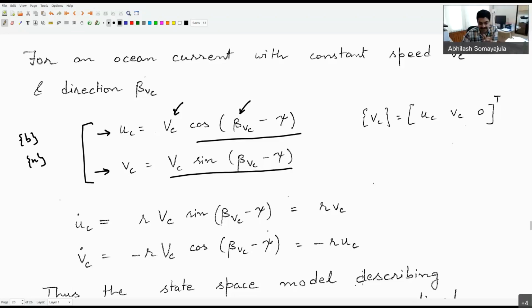Just understand that when I'm taking a difference between the actual direction of the current and my current heading, that is telling relative to my ship's bow where the velocity is pointing, isn't it? Then what am I doing? I'm taking its components with respect to that angle, so one along this and one along this. So which frame would that be in?